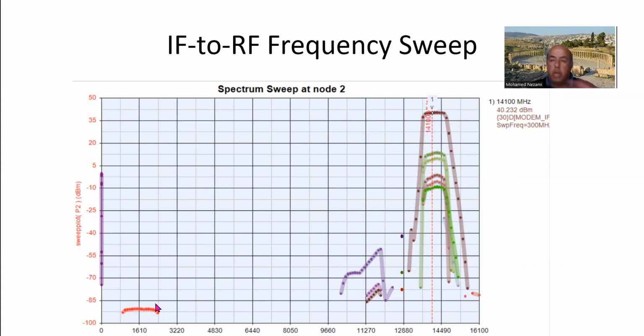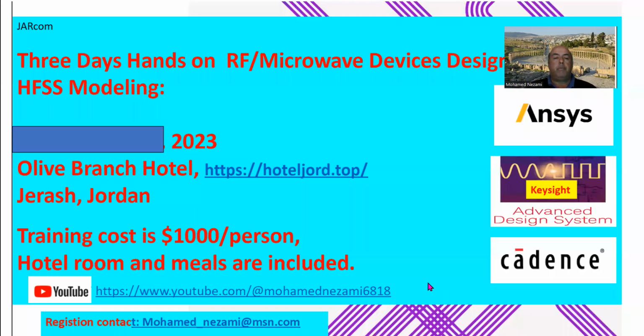We're not talking about the next step of taking this design and going down and starting to do stuff in the ADS active devices. Then we have the IF leak in there at the output, okay? And then we have the actual desired signal in here. We have the image in here and a few other replicas of the image. We have also some in-band signals that are coming in here, and we can go into the tool and start analyzing where these are coming from and trying to minimize these, okay?